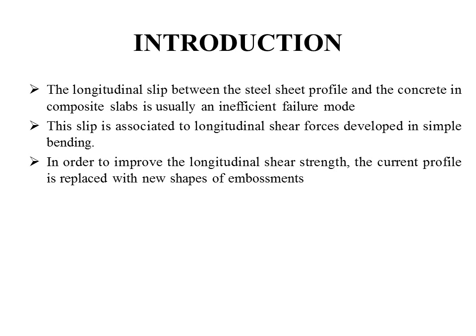In order to improve the longitudinal shear strength, the current profile is replaced with the new shapes of embossment. For that only we have selected a different embossment that will provide a maximum shear key action with the sharp edges. That will provide a maximum slip resistance. Apart from that, by reducing the spacing of the embossment, we can achieve a maximum grip.